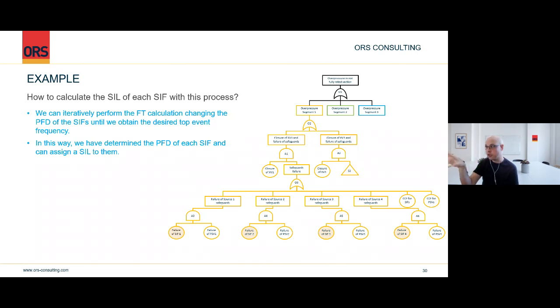And maybe once you develop your fault tree for your system, you realize, wow, we have one basic event, which only has one protection layer between us and an overpressure event, for example. So then you can work on that scenario, because also when you calculate the fault tree, you will get the numbers for each of these gates, right? So you will get the calculation, the result for each of these gates, and then you can see which of these gates contribute more to the top event, and you want to focus on reducing the frequency of those gates then. So yeah, very, very interesting coming from Solak.